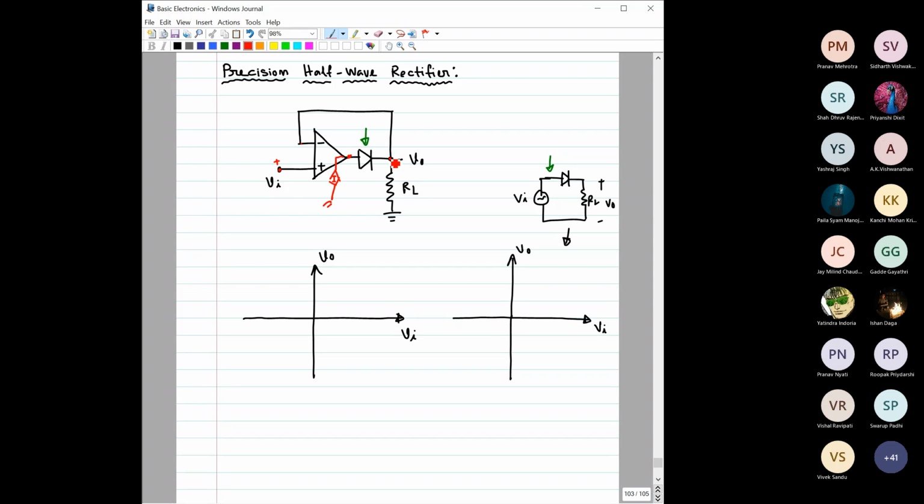here, right? What will happen to this voltage? Say this voltage is V internal. So V internal will adjust accordingly such that this voltage is equal to this voltage and this diode is on. Remember, this V internal will adjust accordingly as you change this voltage so that this diode has to be on and this potential would be equal to this potential.